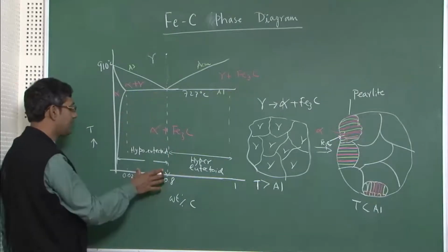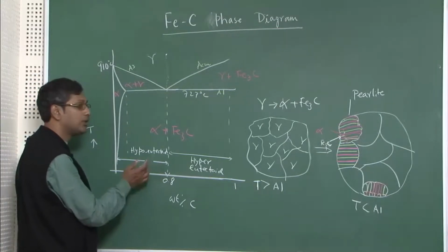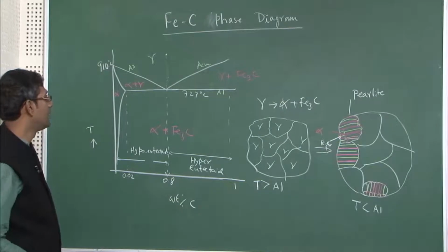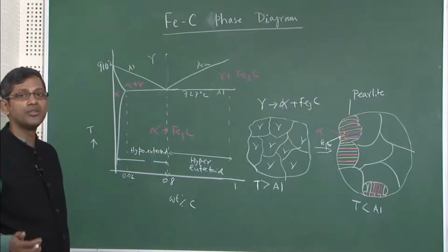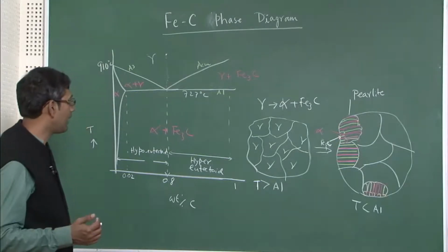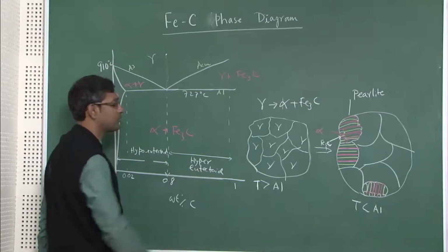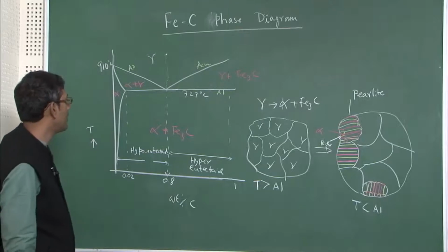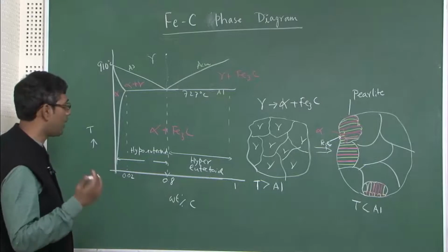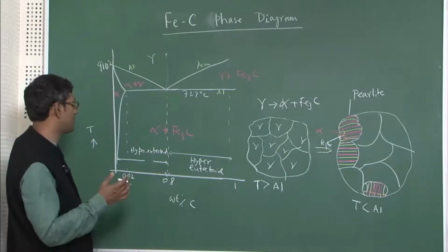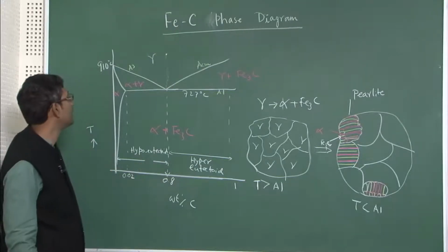Remember, most of the steels in the world, almost 1000 million tons, are produced with a composition between 0.2 to 0.5% carbon, and very little steel is produced that is hypereutectoid. Mostly steels used for knives, cutlery and very hard objects, like razor blades, have compositions close to 1% or 0.8% carbon. But all the steels used for structural applications like bridges, houses, any building, or ship building, basically fall in the hypoeutectoid range.